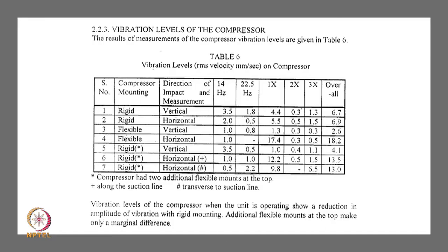So vibration levels of the compressor when the unit is operating show a reduction in amplitude of vibration with rigid mounting. Additional flexible mount at the top makes only a marginal difference. So there is no need for the complexity of holding it on top.